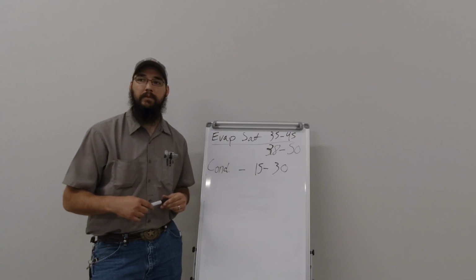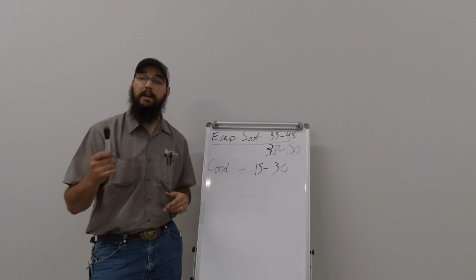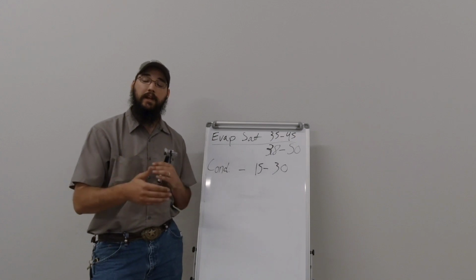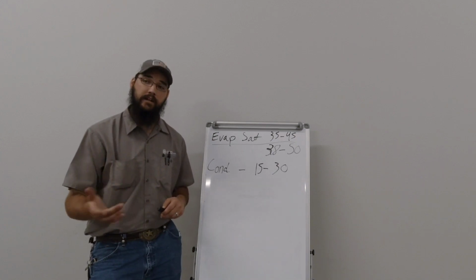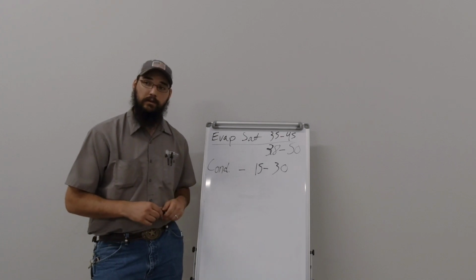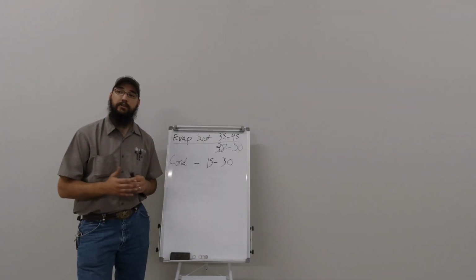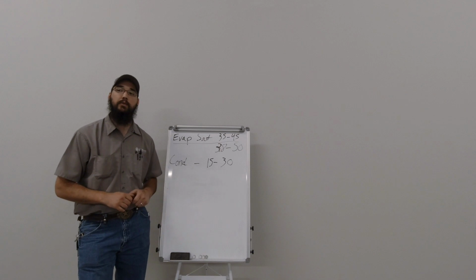And so they need to know the outside. What they're paying attention to is they're taking a load calculation on the indoor. And they're factoring in the indoor wet bulb as part of the load calculation for the charge to help you tune it in.